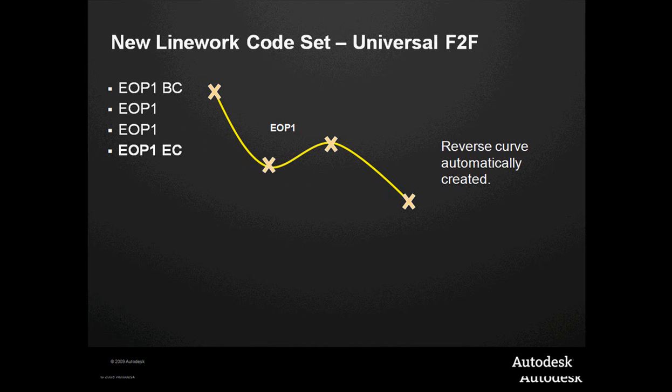So if we're going to do QA, QC, my guys go out and collect a whole bunch of stuff. I can grab the edge of pavement and I can review all of the slopes along that entire segment. 1.5%, 2%, 1.5%, 16%, what happened there? Then I can start to look and see the elevation when we shot, did they change the prism height, but it'll maintain all of that for us.